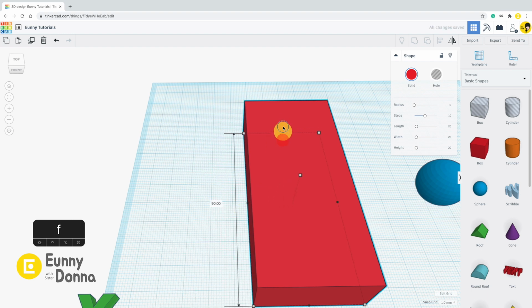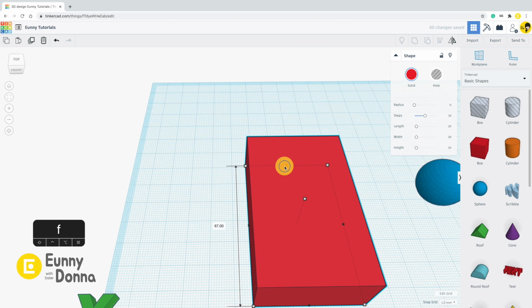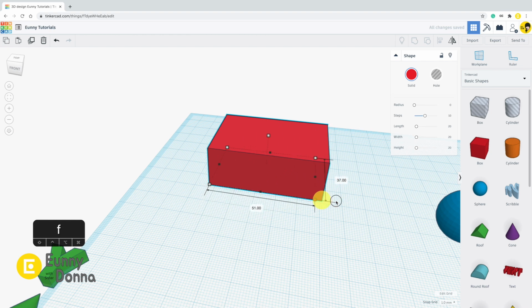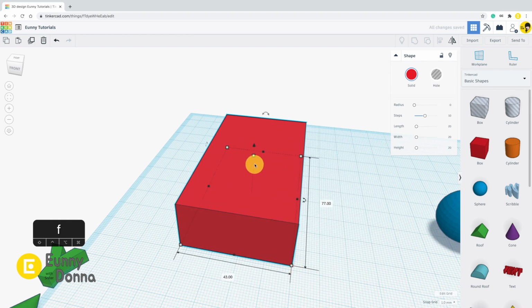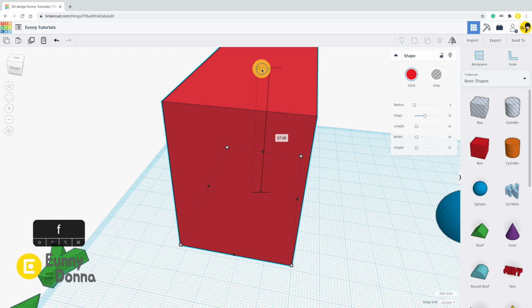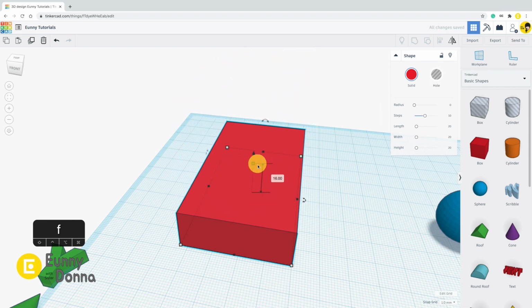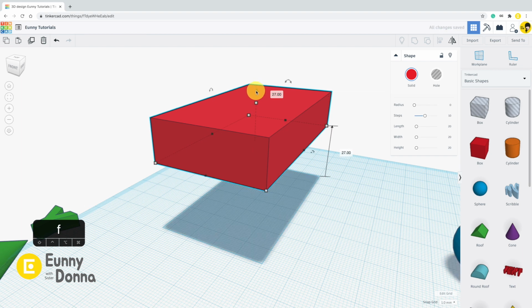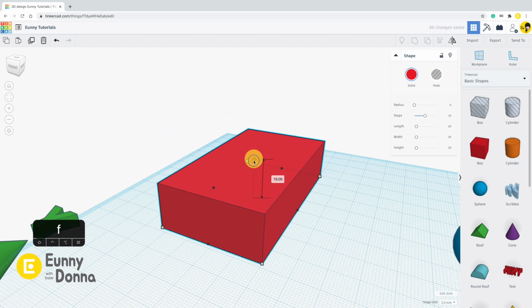Did you recognize that you cannot change the height of the shape with the points we have tried? For the height, you need to find this white point in the center and drag it. Then you can make it higher or lower. As you can see, anchor points are scattered everywhere, and the black triangle for movement on the Z-axis is located very closely. Hence, you need to click the right point carefully for the proper function.